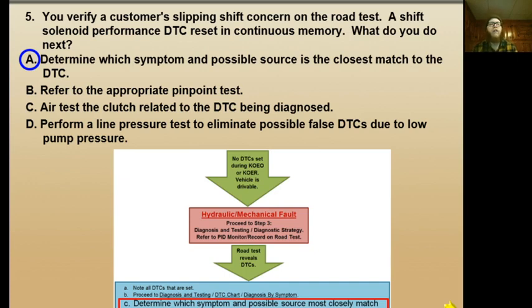And if so, how much information can I get out of it before I take it out, so that when I do go through it and fix it, I have the best potential to find the root cause of what caused any damage, so that we don't put it all back together with the same valve body, let's say, and then the thing roasts itself once again, and then we have to do two internal repairs. Hopefully on that second go through we would have found that the solenoid body or the valve body was having an issue.